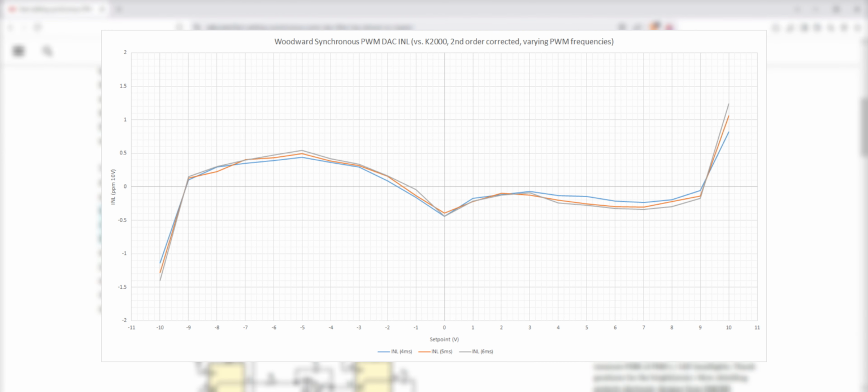Also dependent on the time constant matching is the settling. Since this is a closed loop system with feedback, the matching can be thought of as a gain factor. When the product of R and C matches the PWM period, the duty cycle and output swing relative to the reference voltages have a 1-to-1 relationship. If the PWM period is larger than R times C, the output overshoots and settling has a slight ringing characteristic. If it is smaller, the settling time is more gradual, and at an exact match, settling takes 2 cycles to 99% of the set point, as described in the original paper from 1970.